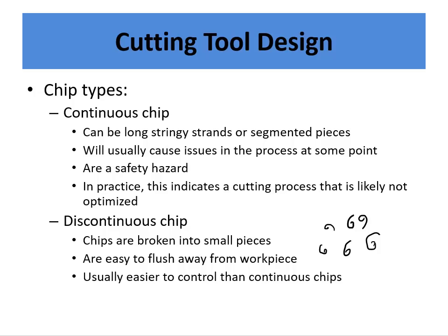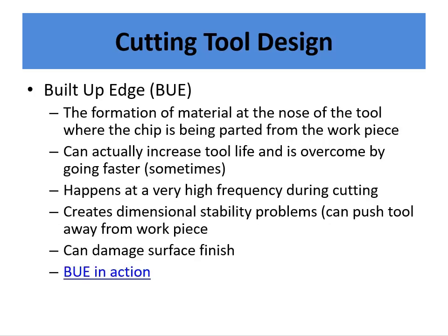That can happen with chips that are broken up into discontinuous chips as well. You normally need to flush them away quickly, but if you have long stringy chips, it's a much more likely scenario. So, built up edge.